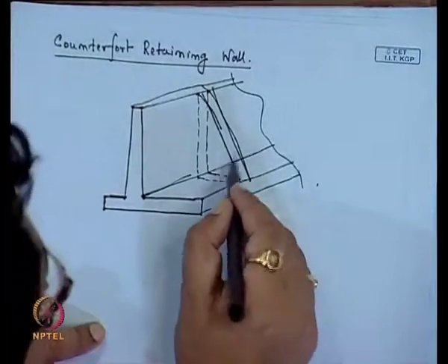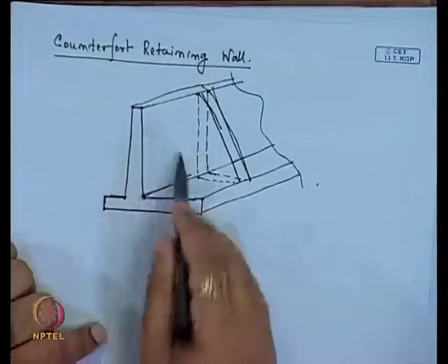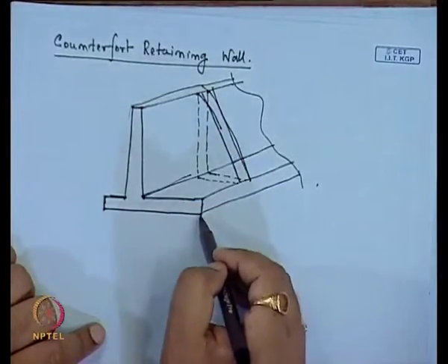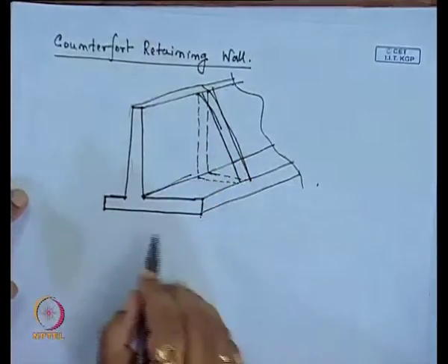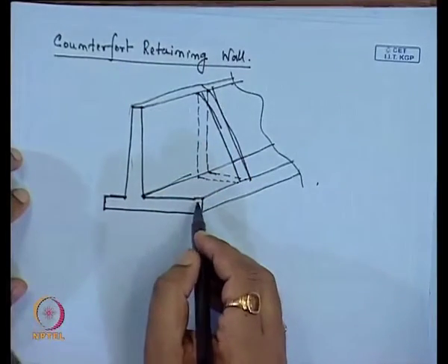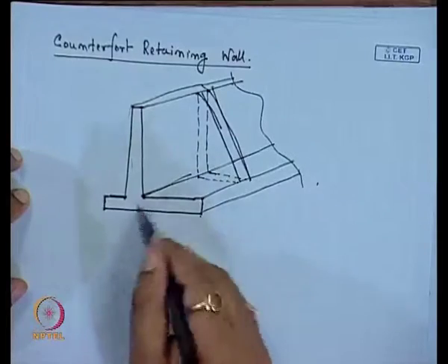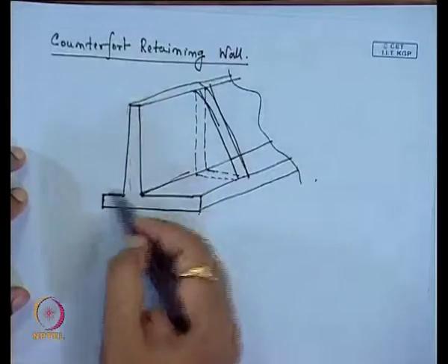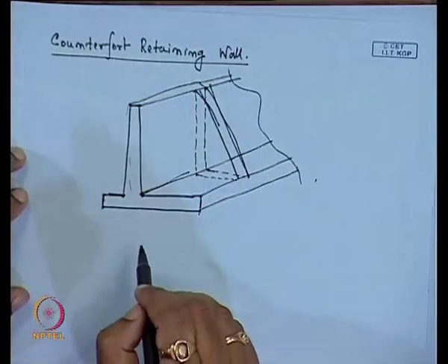When you determine the dimensions of the front portion, it is similar to the cantilever retaining wall. So, the same as we discussed for the cantilever retaining wall design procedure, we can determine the dimensions of the counterfort retaining wall also.